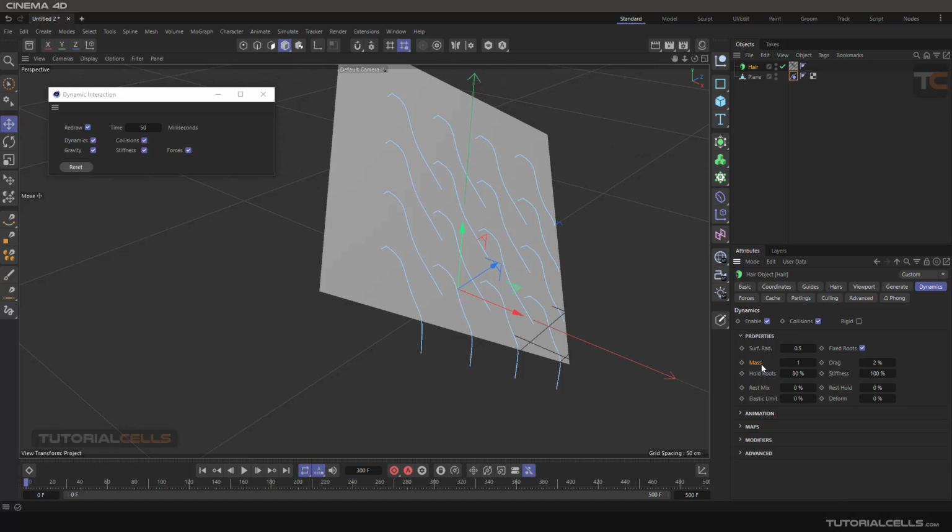You can better understand it that way. Actually, it enables or disables the dynamic effect along the hair from root to tip. Means if you paint a hair vertex at some points and assign the map to 1, it will be active in the dynamic effect, but at 0, it does not affect the dynamics.